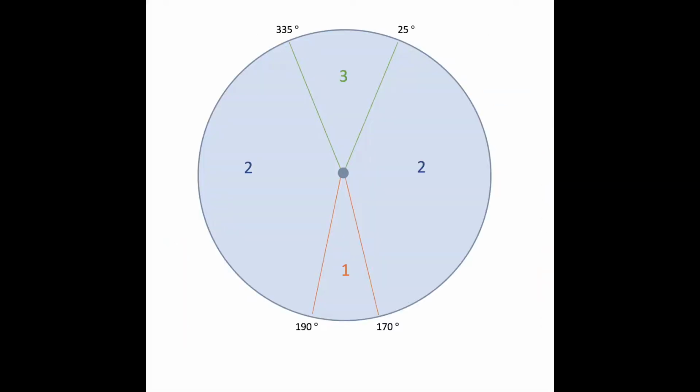Since we want the robot to behave differently depending on the position of link 2, we section the robot into 3 states. State 1, at the bottom of the pendulum, is responsible for the swing up. State 2, on the sides of the robot, is an in-between state, and state 3, at the top of the pendulum, is the balancing state.